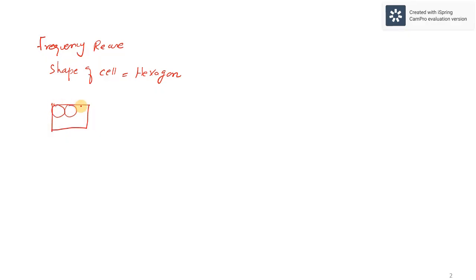So these areas are uncovered, and sometimes there is a possibility of interference like this. And if you are going to use a triangle like this, all regions will not get the equal amount of power. The square can also be used, but if you are keeping the tower in the center, this capital R is not equal to this R, and hence we are not using it. Therefore, the final thing which the standard approved is hexagonal shape.